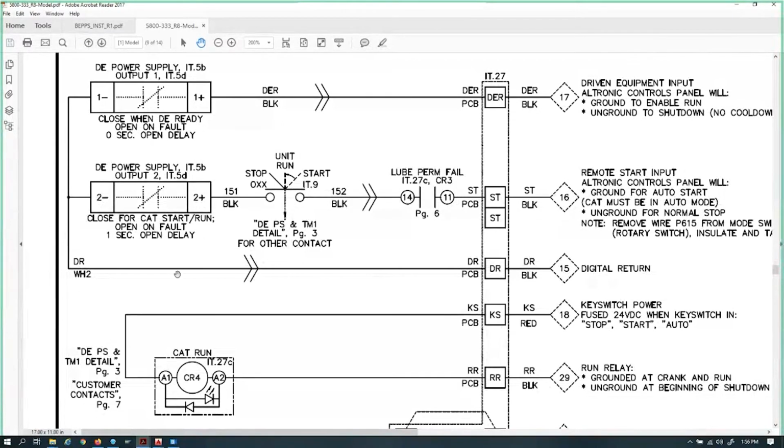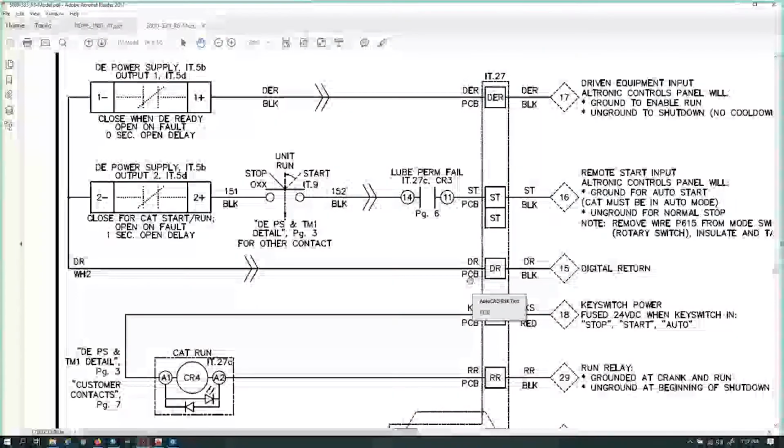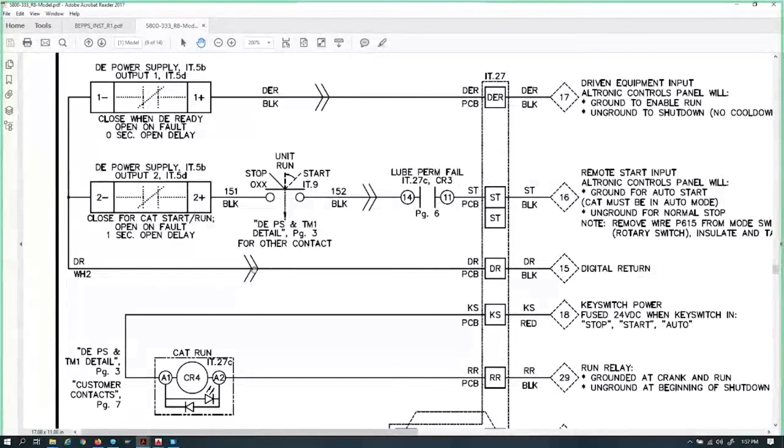It goes through our circuitry and lands at DR, item 27, which if I look it up in the BOM is the relay PCB board. It goes from a black wire, transitions through this terminal. Now it's still this circuit, but the circuit's on the PCB, so it's part of the printed circuit. It leaves through a wiring connector, the harness, in this case wiring harness 2, and it wires directly to output module 1 and output module 2 on the negative side.